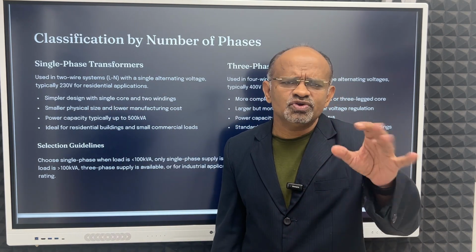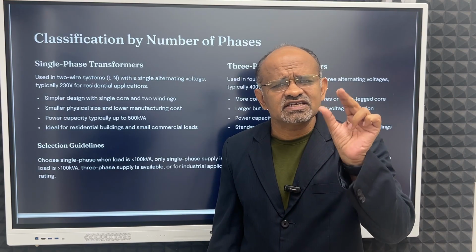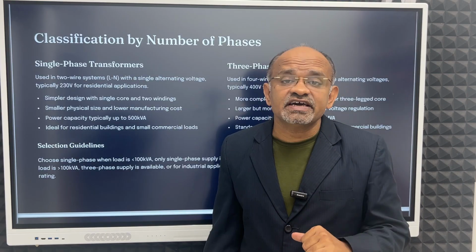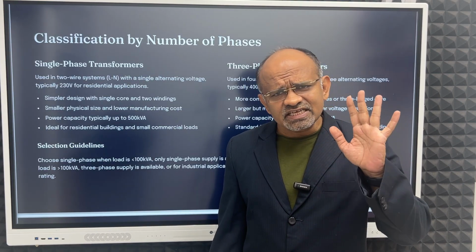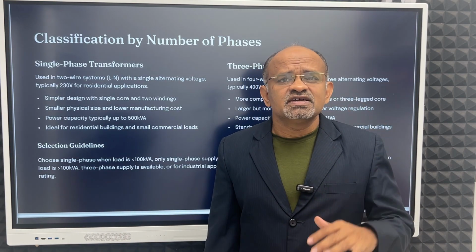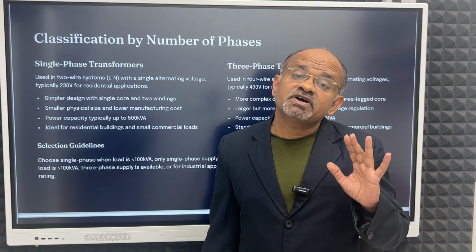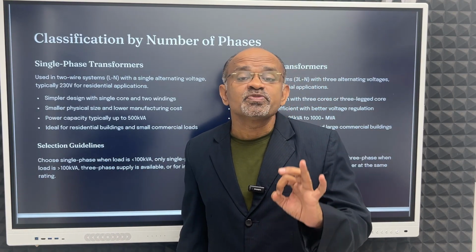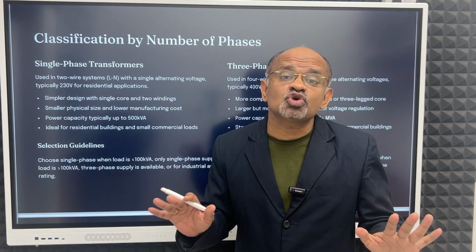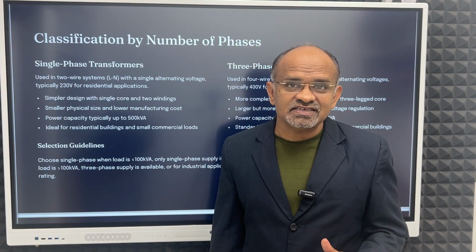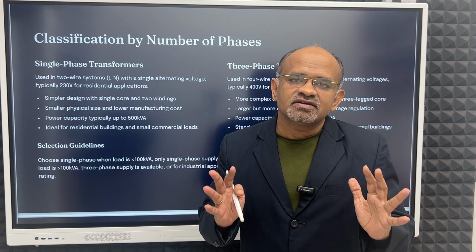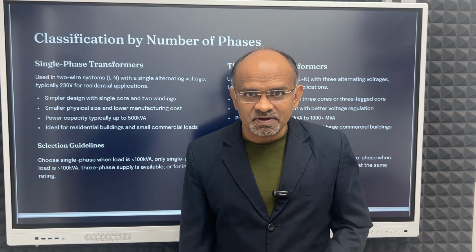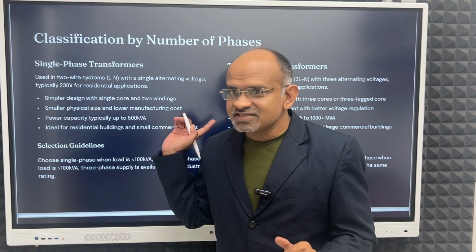But somewhere like in UPS or other electronic devices, small things, the small currents can be managed, so single phase transformers are there. Even now, for special purpose machines, single phase transformers are used. But these are expensive, and managing high current is not a joke. I squared R losses will increase. Since current is high, managing heat will be a problem in a single phase transformer. Now you understood the difference.